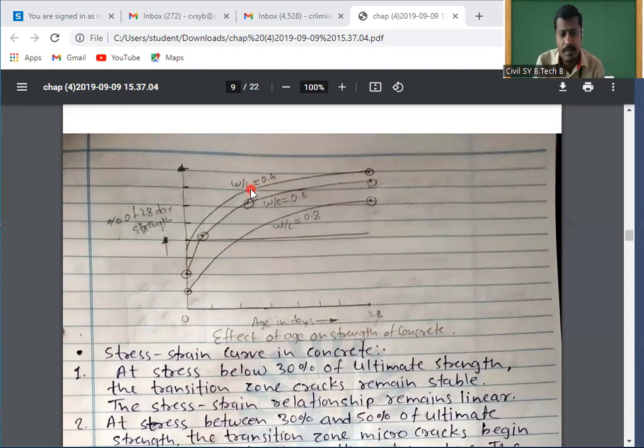Okay, so it is recommended to use the designed or calculated or the minimum water cement ratio as far as possible. Minimum does not mean so minimum that your concrete becomes completely harsh. We require the concrete to have some workability. So you have to select that water cement ratio. Okay, again as I told you, we will take this part in chapter number 7, how to calculate the water cement ratio exactly for whatever concrete mix you are interested to prepare. Okay.